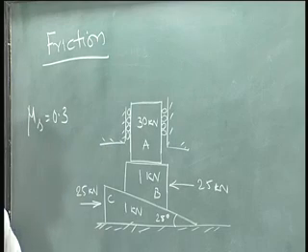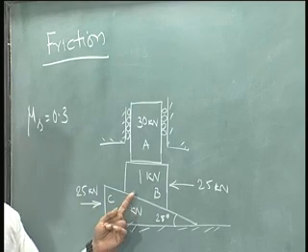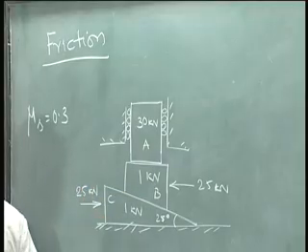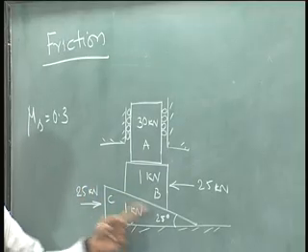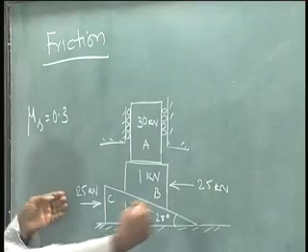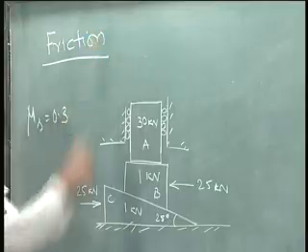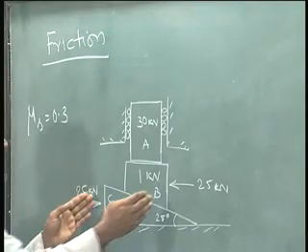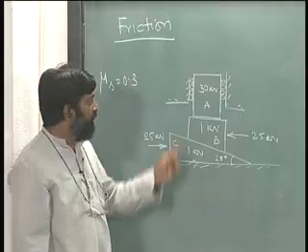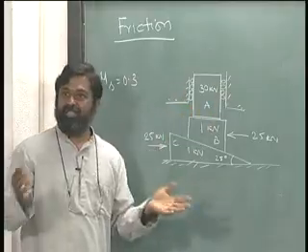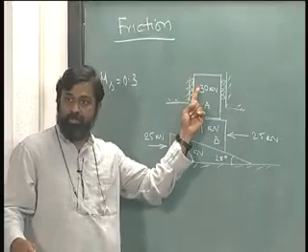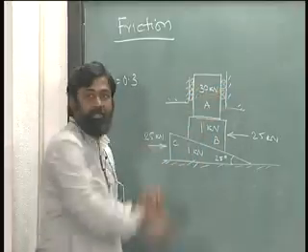Whatever the case may be, what they have done is they have 2 blocks here with a slanting contact between them. Now this is a wedge, this is another wedge, but in a block shape. So if I push these 2 this way, this should go up, and if I gradually release this, it will come down. That is the engineering problem. We have rollers over here, so that there is no friction along this, it is only a normal reaction that comes on the sides of 30 kilonewton.